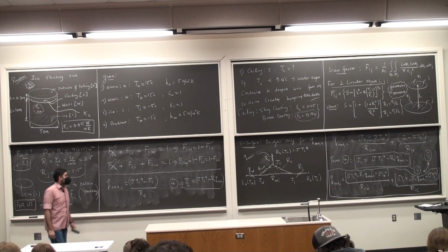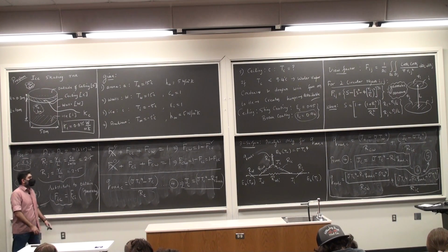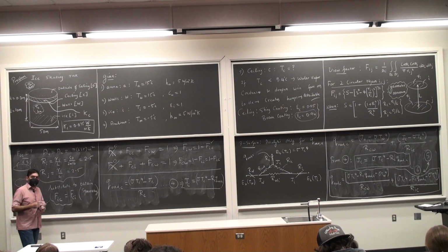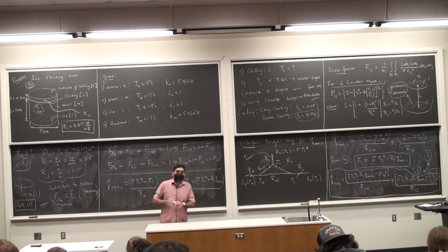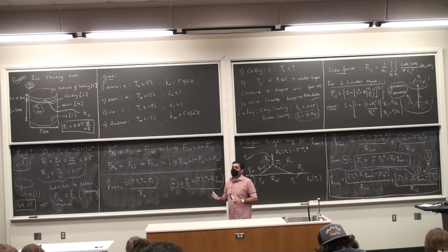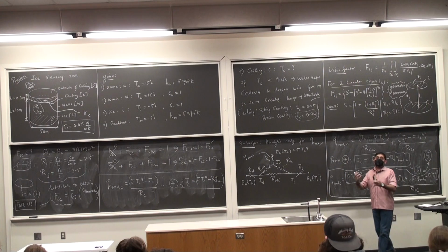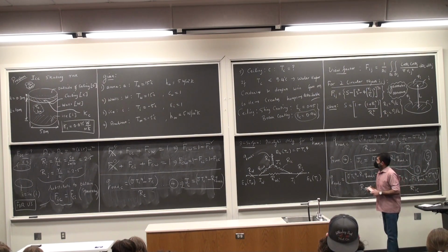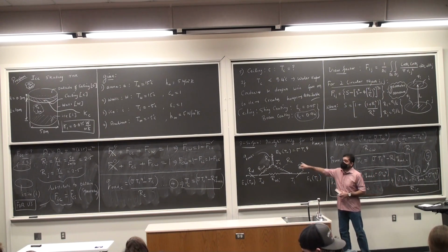So we have a couple more minutes left. Is everybody seeing the basic idea of what we are doing here? Essentially manipulating a lot of things. Okay, we focused on the ceiling because that's where our area of interest is. On the ceiling, there is conduction heat transfer, there is convection heat transfer, there is radiation heat transfer between the ceiling and the enclosure, which is the wall, and the ice. All of that culprit is this guy Q radiation C, which comes from this network that we have drawn here.